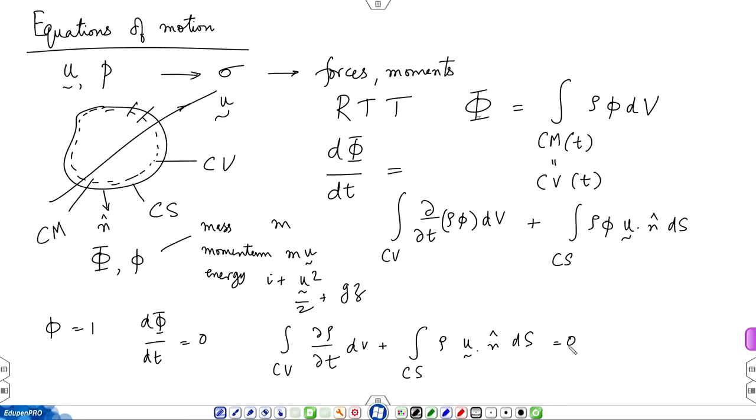So, I mentioned last time that integral equations generally are harder to solve compared to differential equations. So, always drive towards reducing our governing equations, like the rigid body problem with m du dt etcetera. It is a differential equation. We want to reduce it to a differential form. So, that is enabled by replacing the surface integral by a volume integral.